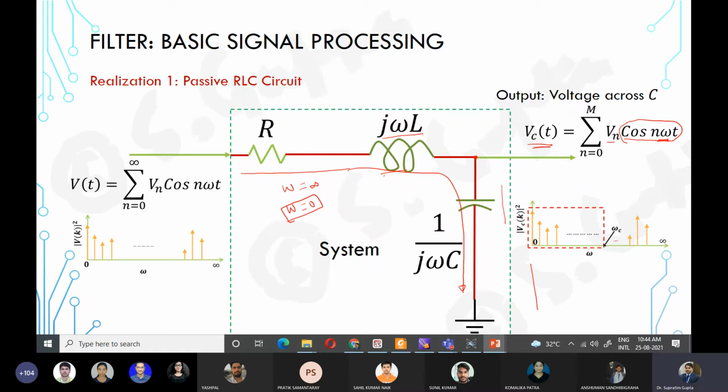If you see the old radios where we used to tune our frequency using a knob, and if you have seen behind the knob, there were a number of discs, and those are basically plates of the capacitor. If you change the overlapping area of the capacitor, the capacitance value will change, and accordingly it will be tuned.